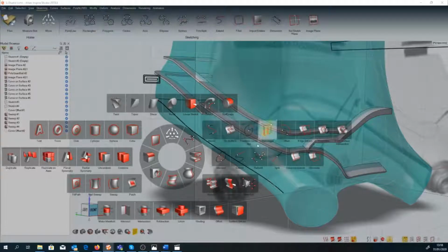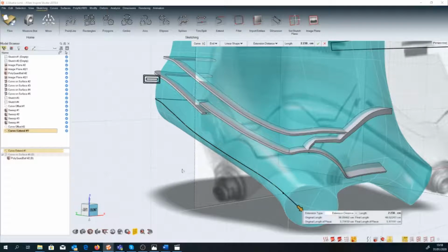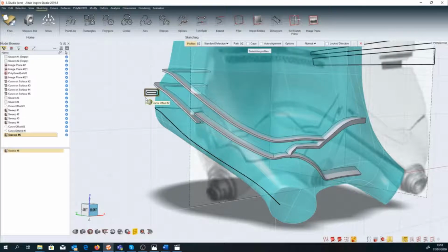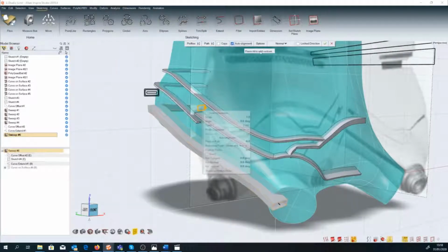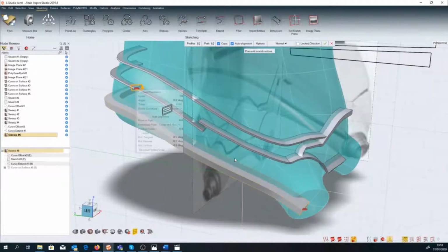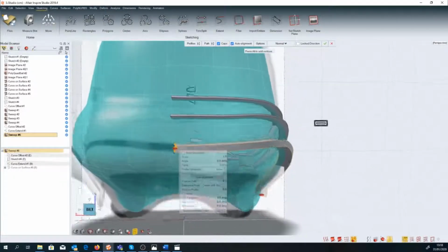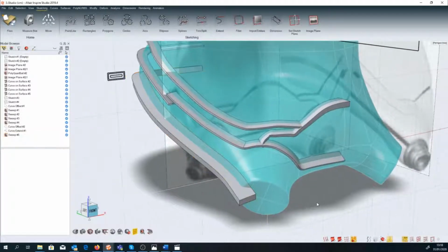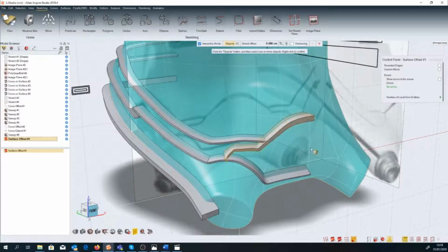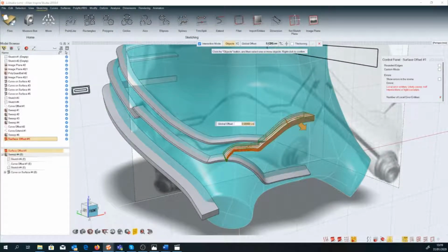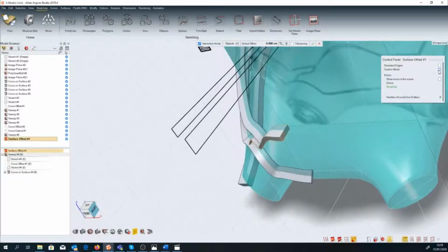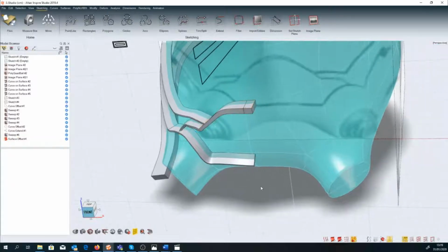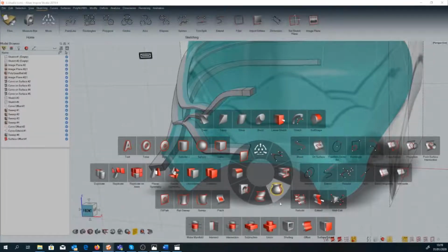The helmet is a symmetric object. Also, the subtraction solid must be symmetric and should be tangent along the intersection plane. So, I will show you a trick to prevent any discontinuity. This case can be fixed in many ways, but I prefer this workflow. I'm going to create a surface offset with the global value equal to 0, and I'll activate the custom option in the guide bar. I'm going to edit the offset of a single face and extend the sweeps over the symmetry plane.